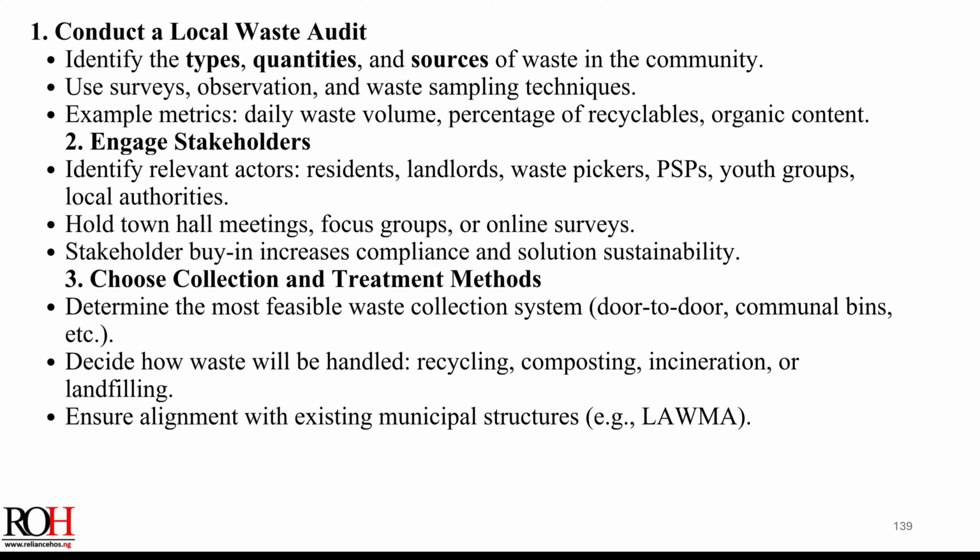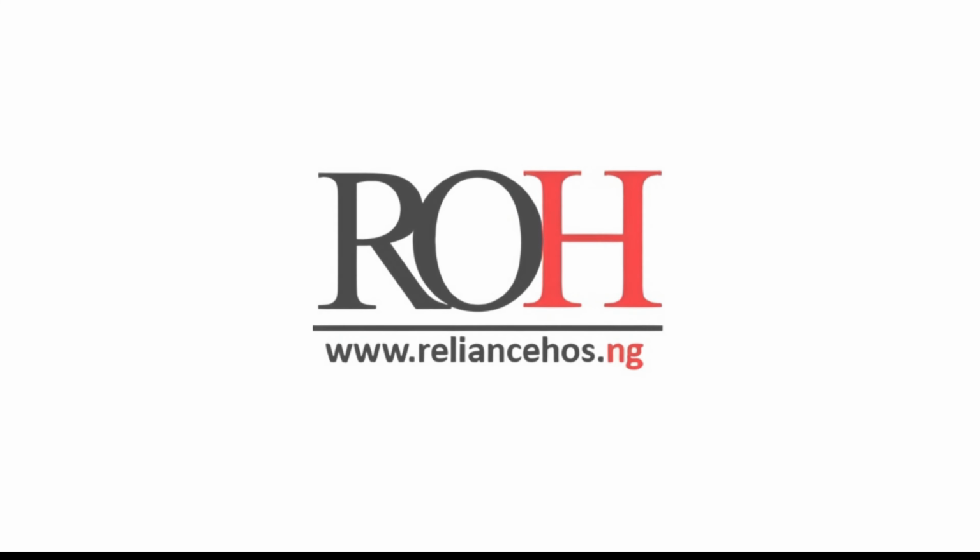3. Choose collection and treatment methods. Determine the most feasible waste collection system, door-to-door, communal bins, etc. Decide how waste will be handled: recycling, composting, incineration, or landfilling. Ensure alignment with existing municipal structures, for example, LAMA.